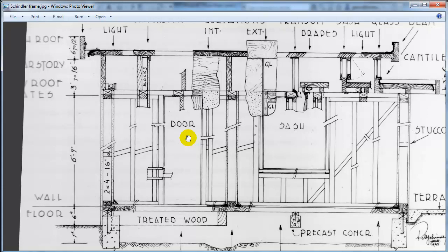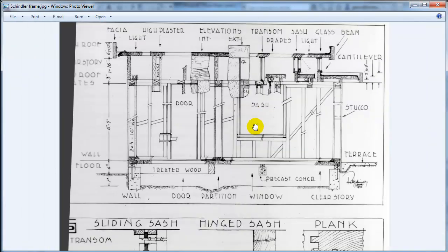That's what makes the drawing challenging to look at, because we're looking at an exterior wall case and the foundation treatment over treated wood. We're looking at a framed floor over just the concrete and the precast concrete beams that we looked at in some of the last sessions. And we're looking at different conditions, a straight-up condition where we have a wood wall over a plaster wall, and some clerestory conditions. There's an awful lot of information here on the section and elevation conditions for the windows and door frames, but we'll unpack that a little at a time.